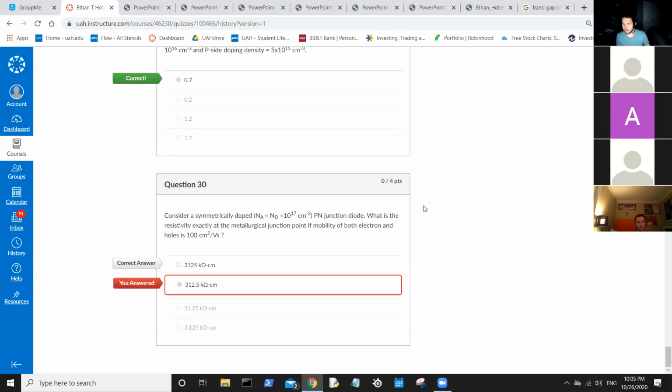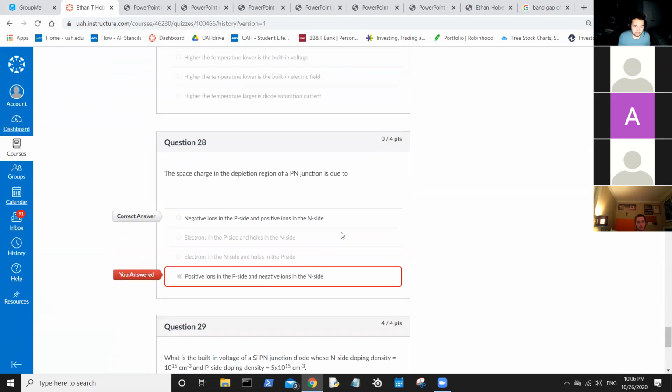Yeah, so here's something you got to remember though. The trick is, at the junction point, it's not always necessarily Ni. You have to solve for that independently each time. We just got lucky that this is a symmetrical one, because it will be Ni when it's symmetrical like this. At that point, since that relationship holds and it's always going to be equal to Ni squared, if the values are equal to each other, then obviously it has to be equal to Ni, but it can change. So you just have to work that formula out each time. The relationship might be different, but it'll always give you a relationship where you can solve for one of them. And since they'll be equal at any given point, you can use that relationship to solve for the other.